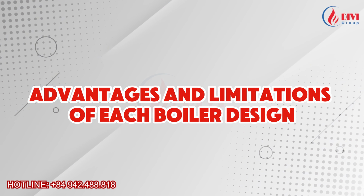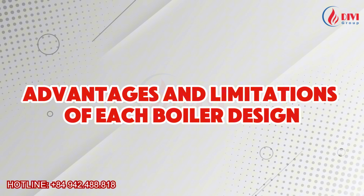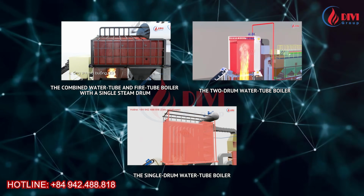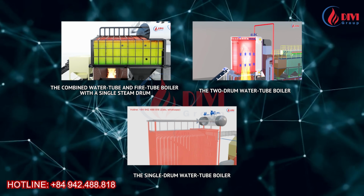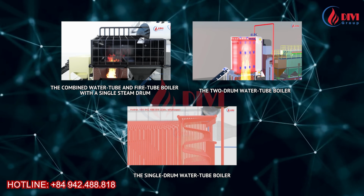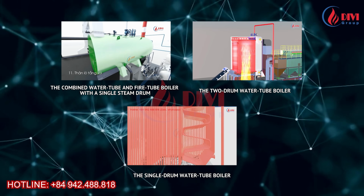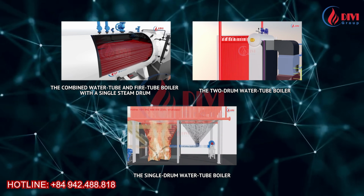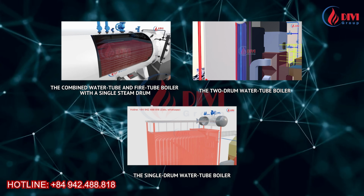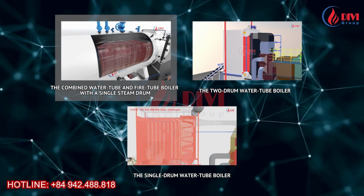Now let's take a look at the main advantages and limitations of each boiler design. I'd like to make one thing clear. Every boiler design has its own strengths and limitations. There is no single design that is the best for every application. The most important thing is selecting the right boiler for your application, considering your steam demand, fuel type, operating pressure, boiler capacity, required steam quality, operating requirements, maintenance needs, and investment budget.